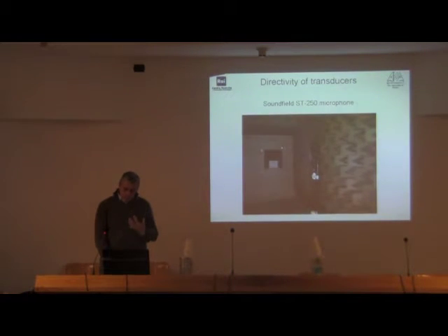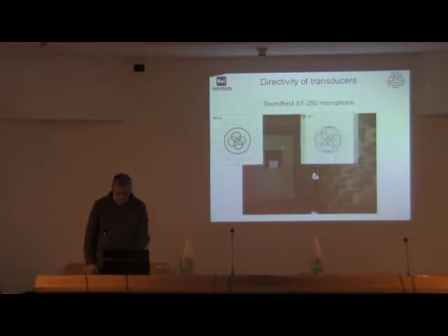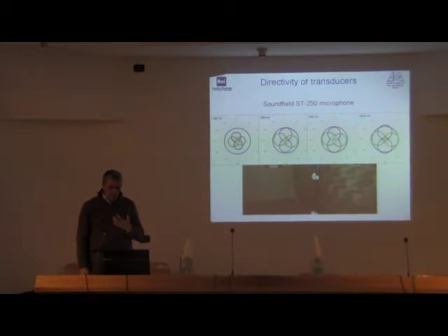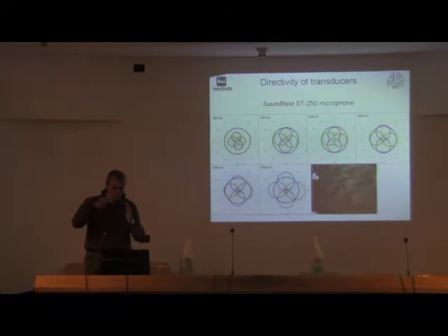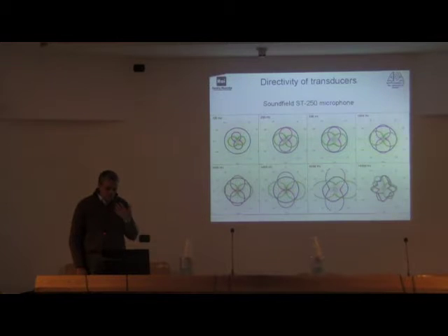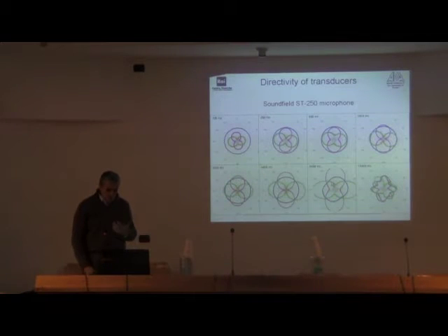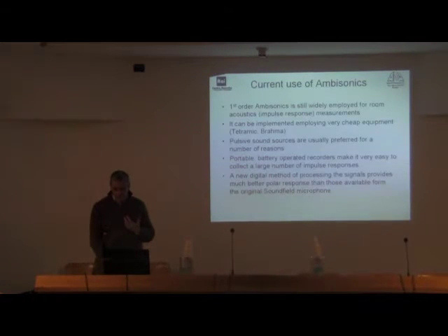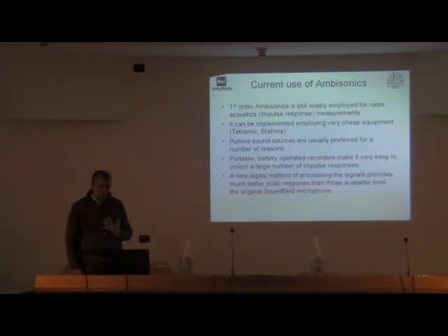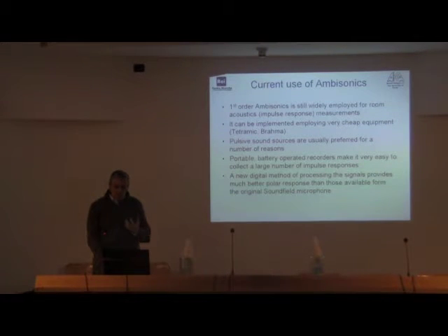This is how an actual sound field microphone behaves, not really very well. You see the polar patterns are not always perfectly aligned with the Cartesian reference, and the amplitude of the velocity component becomes very big, far too large at high frequency. So it's not working very well. But we managed to solve this problem, creating a digital approach for creating the signal from the capsules, which is already a very first application of virtual microphones.